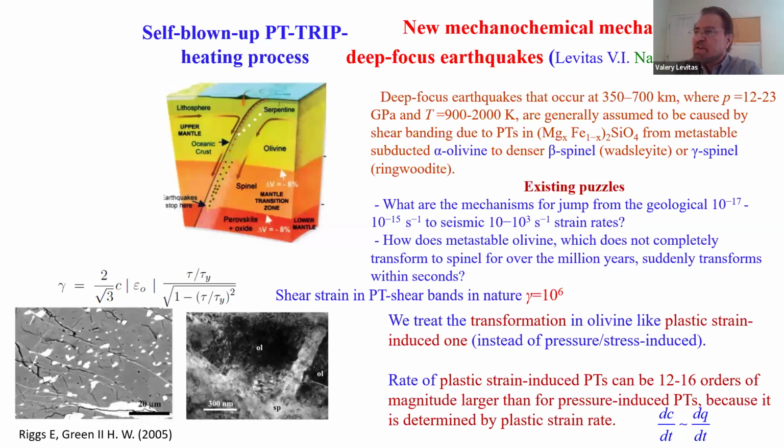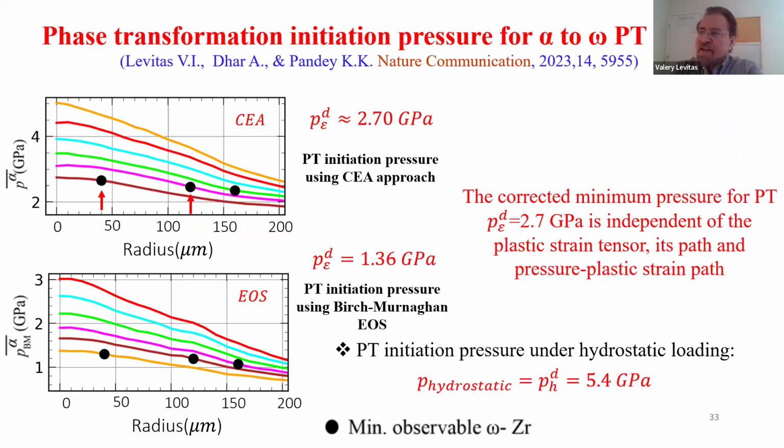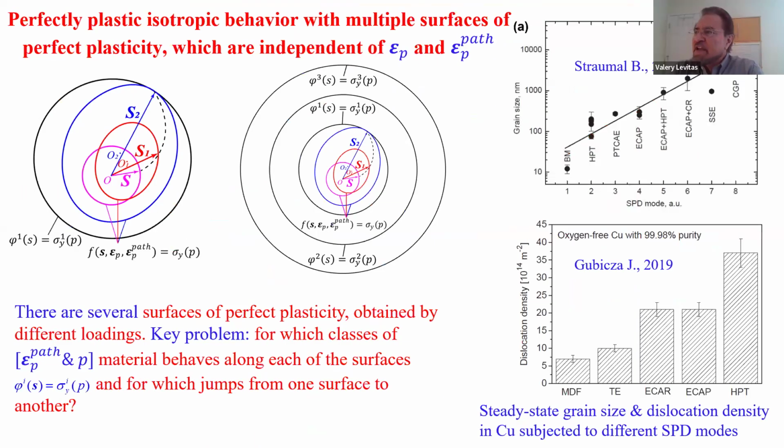No, because even in high pressure torsion to produce nanograined materials in metals, you see dislocation density 10 to 14 and an order of magnitude higher. So even 10 to 15 does not cause amorphization. This is for metals. For geological materials, it depends. For example, we produce severe plastic deformation for olivine, and we did not observe amorphization.